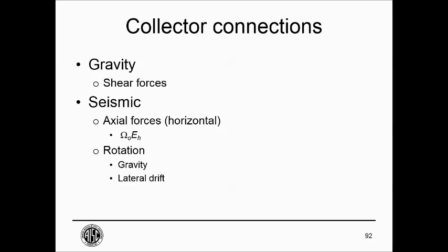And we still have to follow the rules that we have for all of our shear connections. We have to be able to accommodate the lateral drift and rotate as required for gravity loads. So all of our simple shear connections in the manual give us 3% rotation capacity. We would like to keep that also for connections we use in the seismic system.